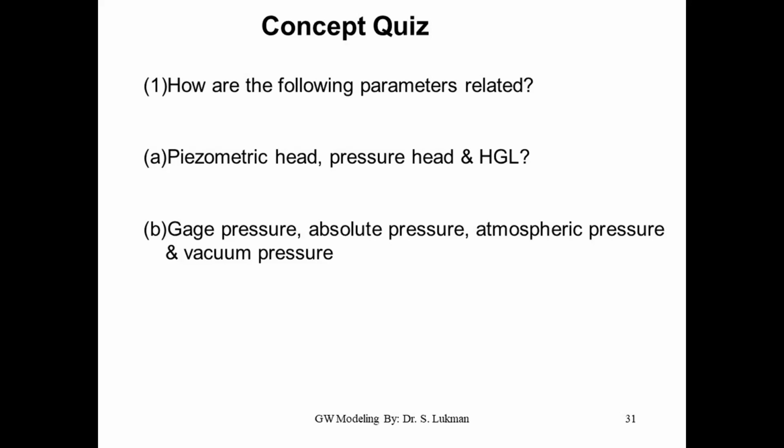The hydraulic grade line is the height from the datum. And how are they related? Piezometric head, pressure head. Not just to show me the equation that relates. Which one? P over rho g, the pressure over rho g. Show me everything. Which one is piezometric head? Which one is pressure head? Which one is the HGL? Z is the piezometric head? No, that's the elevation. Yes.